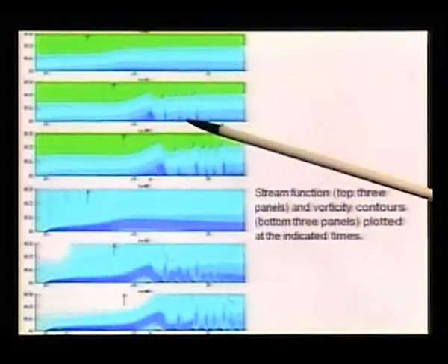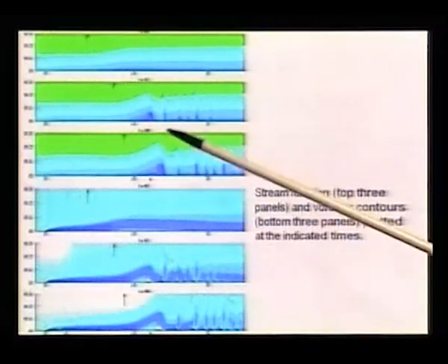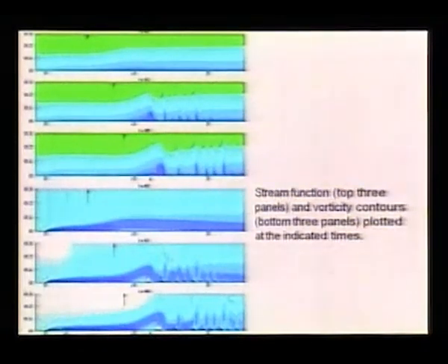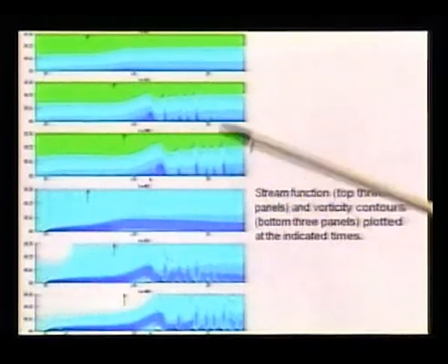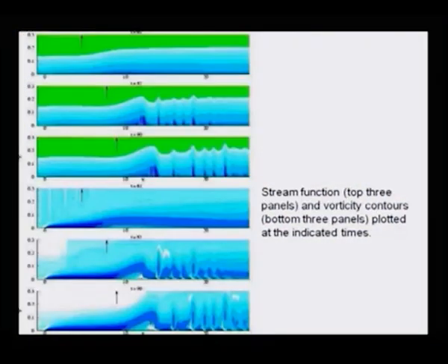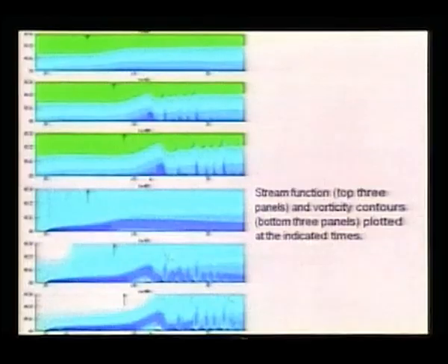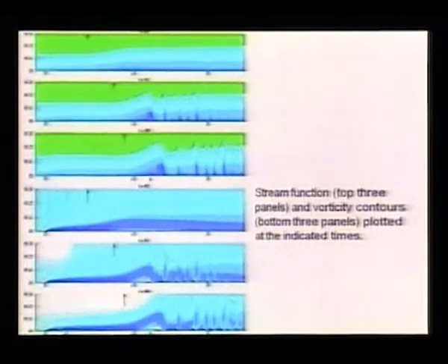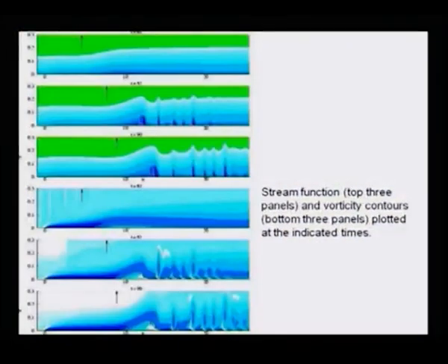From this you can see this undulating streamline structure here, right. So, you can see that there is some kind of vertical eruptions taking place from inside the shear layer. Certain structures pierce through, and this is what we are calling vortex induced instability. And you can see similar vertical eruptions in the vorticity contours. Okay. So, I think I will stop here. In the next class we will give a theoretical model of how it creates this instability.